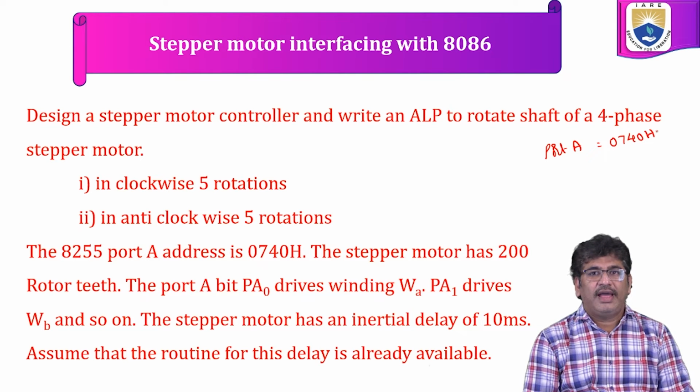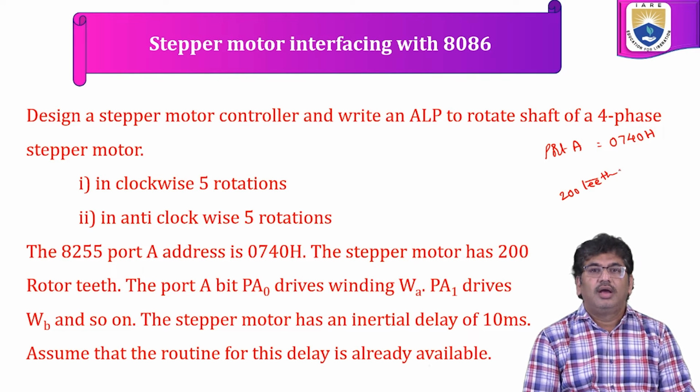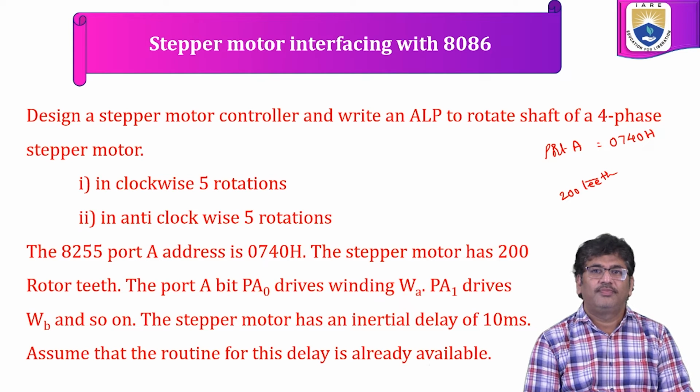The stepper motor has 200 teeth, and port A0 is connected to winding A, port A1 driving winding B, and so on. The stepper motor has an inertial delay of 10 milliseconds. Assume that the routine for this delay is already available.